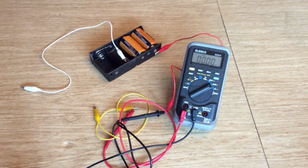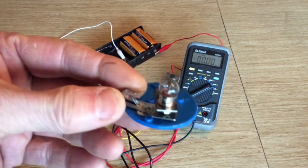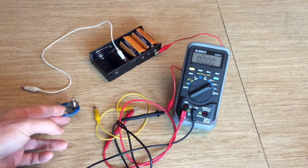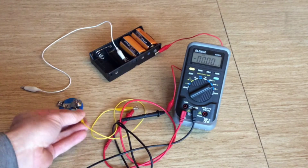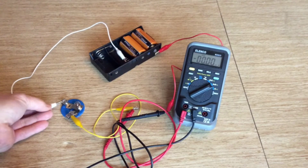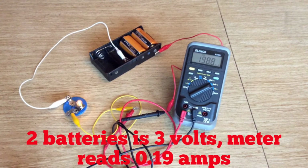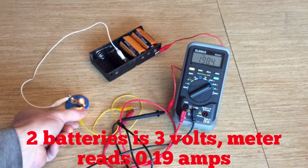Now, guys, if I take this round bulb and I place it in here, I'm going to hook it up very carefully. You see that the light goes on. You can also see that we're reading about 199 milliamps. It'll fluctuate a little bit, but it's about 199 milliamps. And please notice the brightness of the bulb.